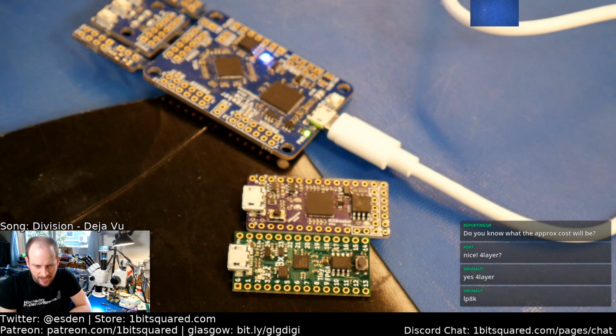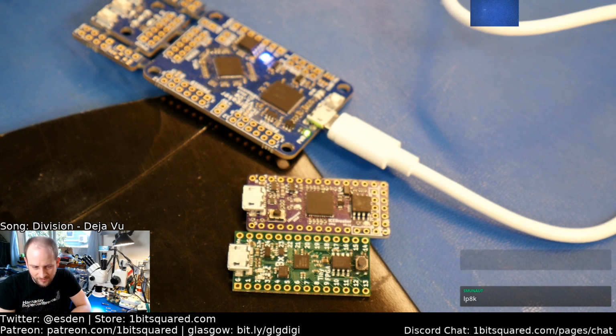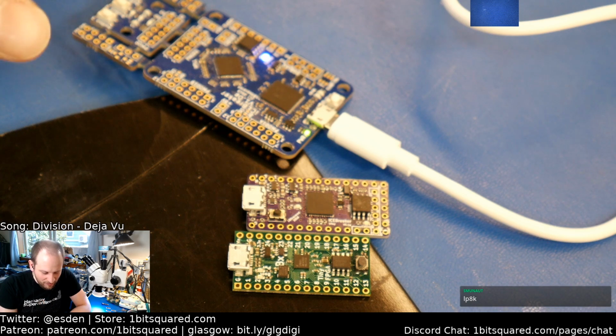UP5K is that the UP5K is designed for lower power. So it is meant to be in very low power applications. That's why it is being used in a lot of cell phones. It was designed specifically for one customer that wanted to put this chip in their phones. It's actually a very big phone manufacturer that is using the iCE40 UP5Ks in their phones. So the problem with that is if you lower the power requirement, you also have a slower fabric.